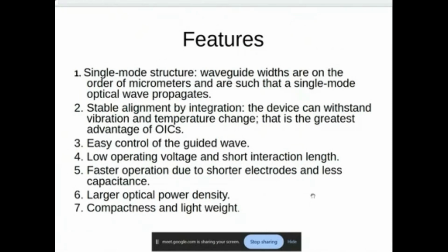These are some of the standard features of photonic integrated circuits. Most of them are based on single mode operation. That's the most important feature. Many of you know that fiber optics goes on in single mode. All the fibers that we see around are single mode. They avoid dispersion. Here it is not that dispersion is our main problem in integrated optics.